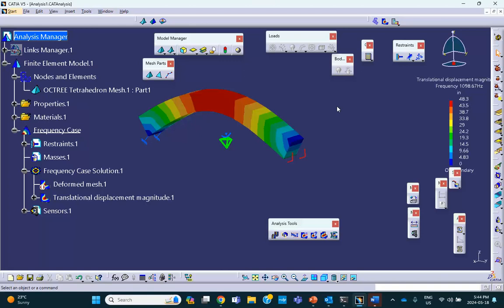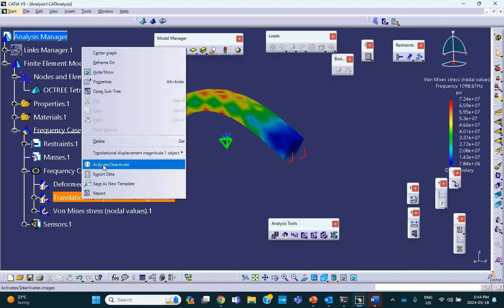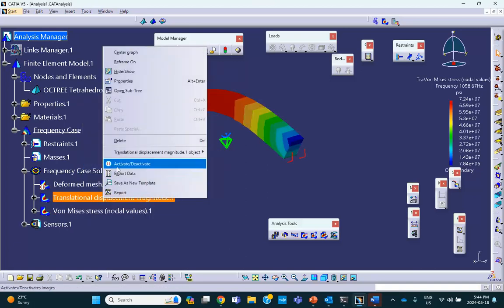This is 48 inches, and that tells you something. If you have any experience with vibration, it tells you that the displacements are totally nonsense. And so are the stresses, because these are stresses which are based on a 48-inch displacement. The shape is okay, and the actual frequency is okay in hertz or in radians per second, whatever you ask for, but these numbers are totally useless. Okay? So let's go back to that first plot. Let me undo this.